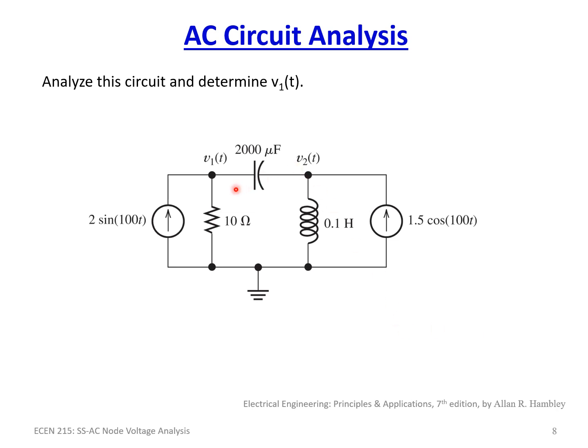So here we're asked to determine v1 of t. In the same process, it's kind of already pre-done for you. In the nodal voltage method, if we're asked to determine, for instance, the voltage across this 10 ohm resistor, the first step is to define a reference node. The reference node for this particular problem was already defined for us. It's right here. So you pick a reference node.